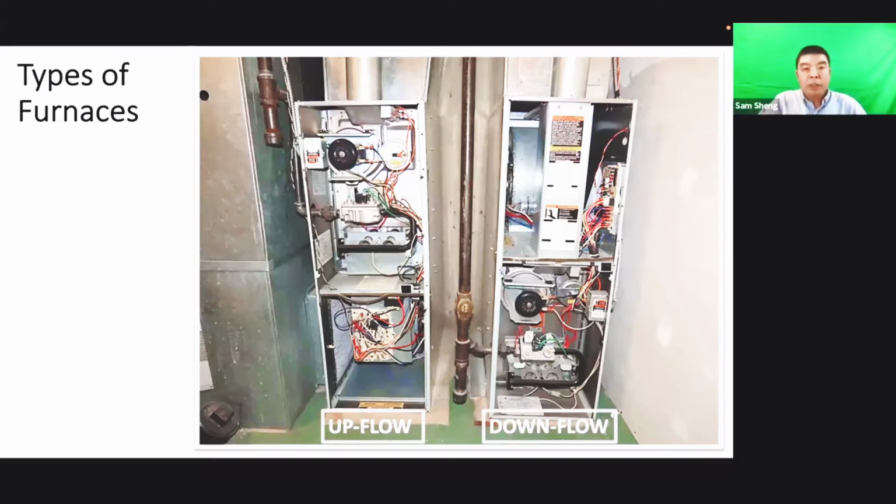Okay, yeah. So sometimes in BC, some areas there's no basement, no crawl space, so they use the downflow furnace. Yeah, so it doesn't matter whether it's a mobile house or a regular house. Yeah, but most of the time the mobile home uses downflow.